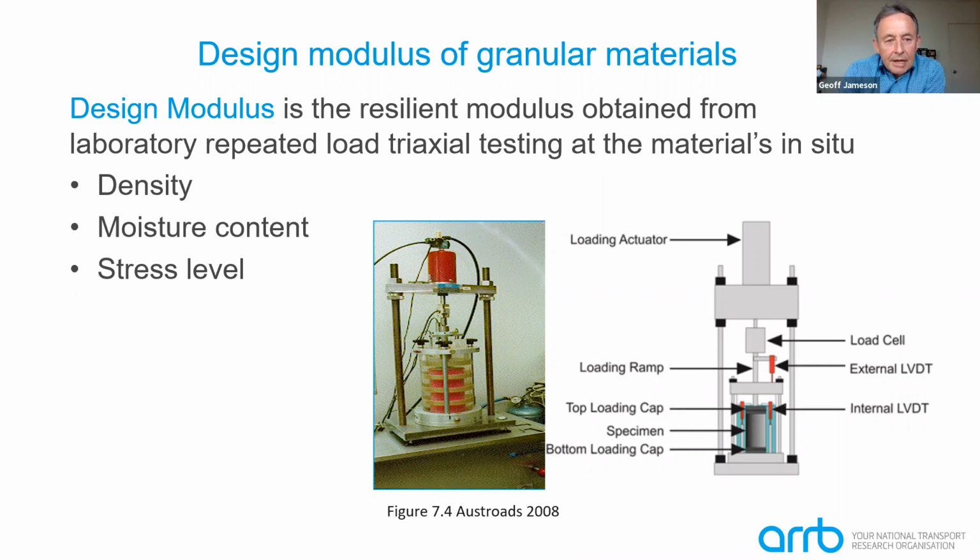So it's an area, again, where there's no real guidance. It's left to the designer to come up with appropriate moisture content for the project, considering all those things like drainage characteristics, the rainfall in the area, the evaporation, et cetera. So it's a judgment made by the designer.